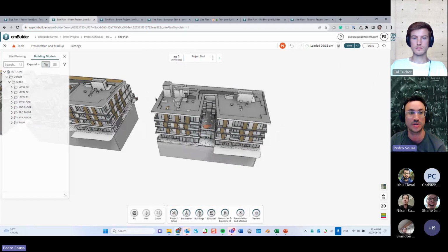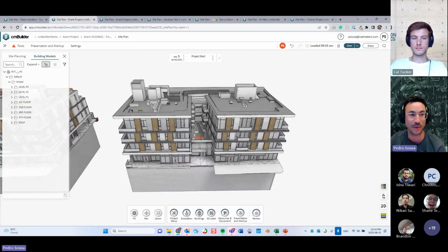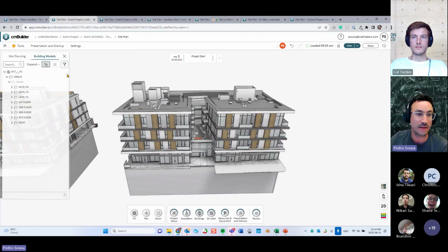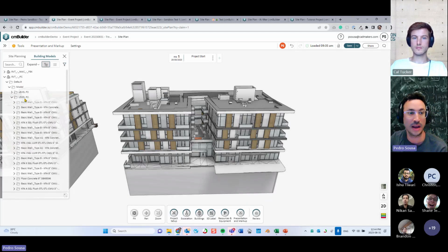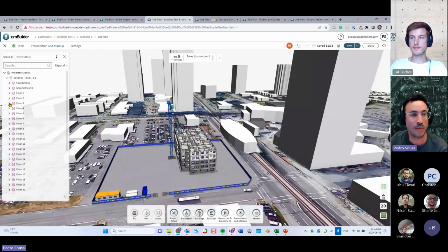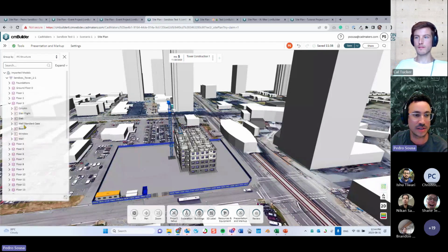So just going back to this scenario where I compare the structures for different file formats, when I open an IFC file, as soon as I open the level for it, it will show everything inside one single flat list. But now you're going to be able to open the floor and see the IFC classes as well. So it's an extra level to help you select things fast and assign them to the milestones.